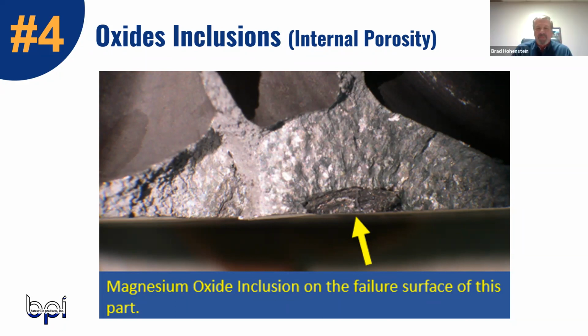Absolutely. As Monty said, the gating controls the speed on a sand cast. Most of the aluminum systems are what they call unpressurized, where you don't want the metal with a lot of force going into the casting. You want it to be choked off somewhere before it starts to enter the casting, so the metal is free to flow into it rather than rush into it.